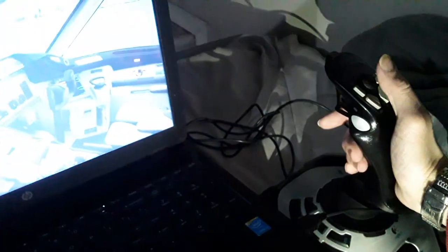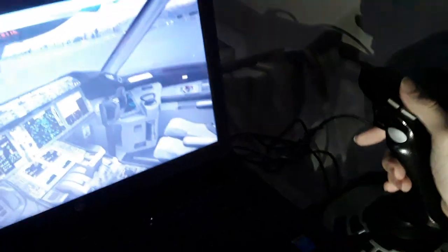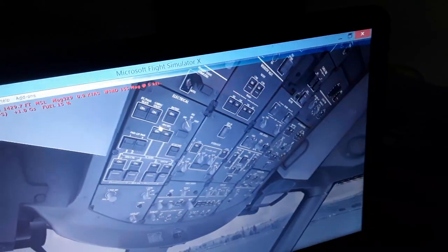Also we have the alpha protection system. When we fly the aircraft with an angle of attack and airspeed that is going to stall the Airbus aircraft in the air, the flight control computers are going to limit the angle of attack of the aircraft at minus 2 degrees usually, and lock the takeoff ground thrust, maximum takeoff thrust lock. So these are some of the features: alpha protection, minimum speed, also overspeed, maximum Mach operating speed, other protections like flap speeds. So we have similar things for the Boeing.